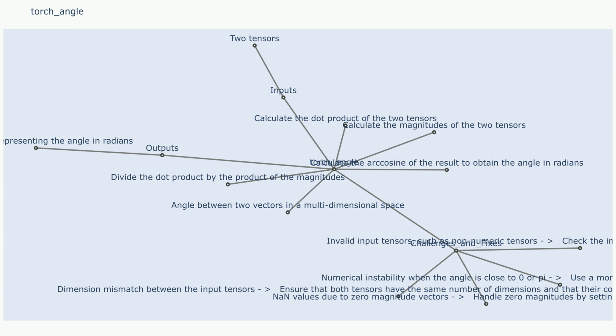Using a jig or guide can help to maintain a consistent torch angle throughout the weld. Practice proper technique. It is important to develop proper welding technique to ensure a consistent torch angle. Use a welding manipulator for complex welds. A welding manipulator can help to maintain a consistent torch angle.